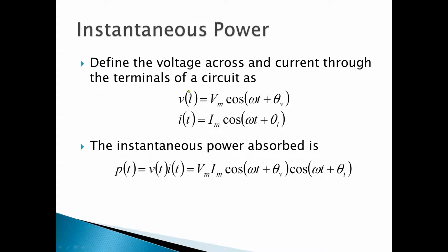So taking my two elements, my voltage and my current, for any element within the circuit, I can determine the instantaneous power that's absorbed or dissipated by the element. And if it's an energy storage element, we know that there's going to be a difference in the phase between the voltage and the current because the impedance of energy storage elements introduces a phase shift between the current and the voltage. Doing this, if I can figure out what the instantaneous current and the instantaneous voltage is, I can multiply the two of them together in the time domain, and I wind up with this function, which is the product of the current and the voltage that describes the instantaneous power.